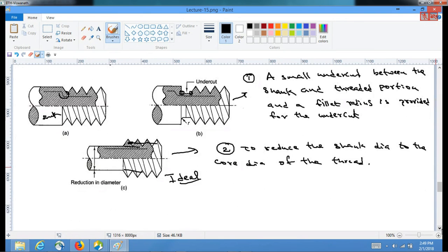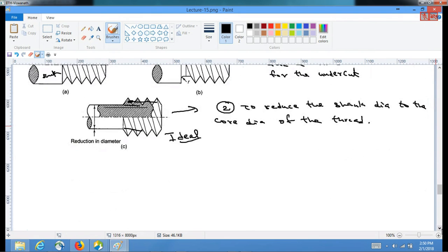So in order to deal with it, we have to account for changes in the elementary equations by taking an additional factor of safety by measuring the stress concentrations. And we need to also know in which cases what is the real stress riser we see, that is obtained using certain tables and charts. So for that, we will see how the application of stress concentration factors works, and after that when you are designing it, we'll provide the necessary tables.